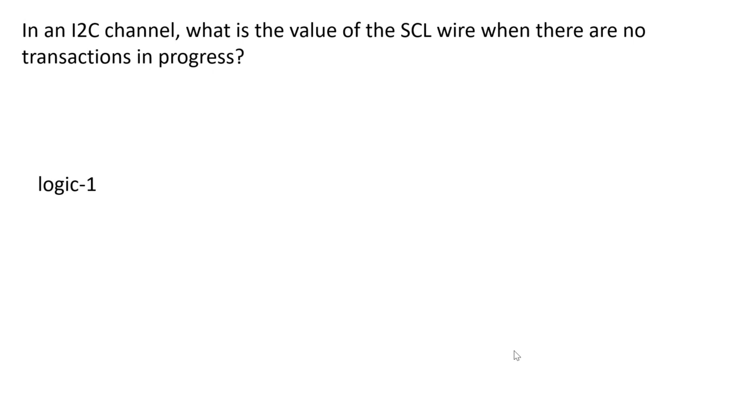That's why the pull-up resistor has to be sized reasonably to not cause too much of a drop in voltage compared to the power supply, but you also don't want that much leakage through it. Generally, they use something like a 10,000 ohm resistor.